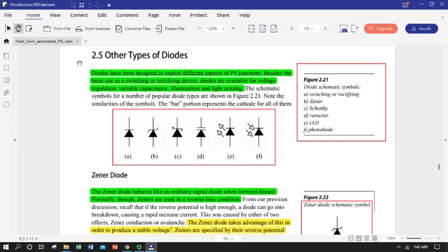We looked at characteristics of diodes, how to read a spec, and then we looked at models for diodes in a circuit in terms of a switch that was open if the diode was in reverse bias, closed if it was in forward bias, and then included an opposing voltage to represent the magnitude of that energy hill.